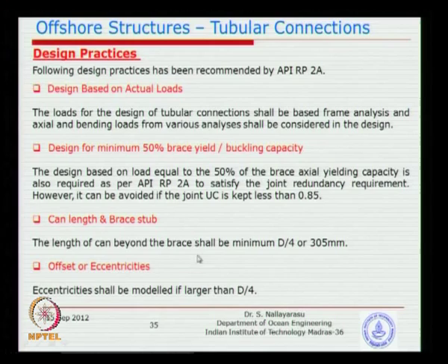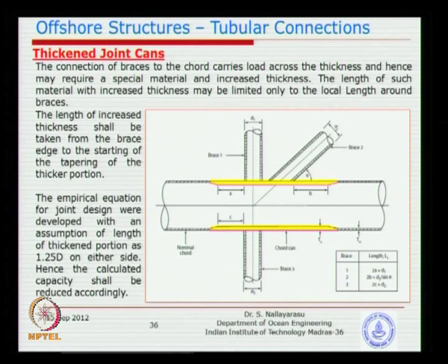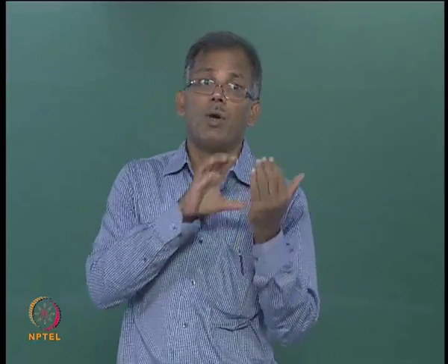And the last one is the design configurations. If you see the sketch you will understand how it is going to be configured, basically the length of the section. If you go to the next page you will see how much is to be extended. Extending the full length is the best, but then you do not have an optimization, because the wall thickness required at the junction is always going to be bigger because of the local effects, whereas for the global effect the member does not require so much thickness.